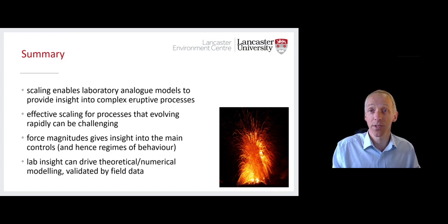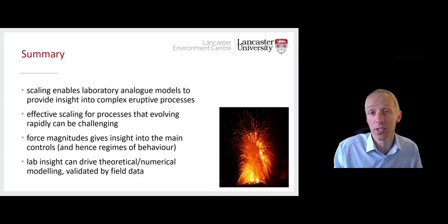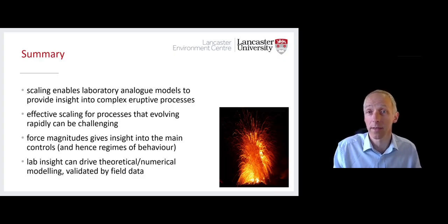When carrying out the scaling for dynamics, it's not normally necessary to directly match dimensionless numbers between the model and the prototype, but rather it's critical to ensure that the dimensionless numbers indicate that an appropriate regime of control is operating. For example, viscous or a mixed inertial viscous regime in our case.